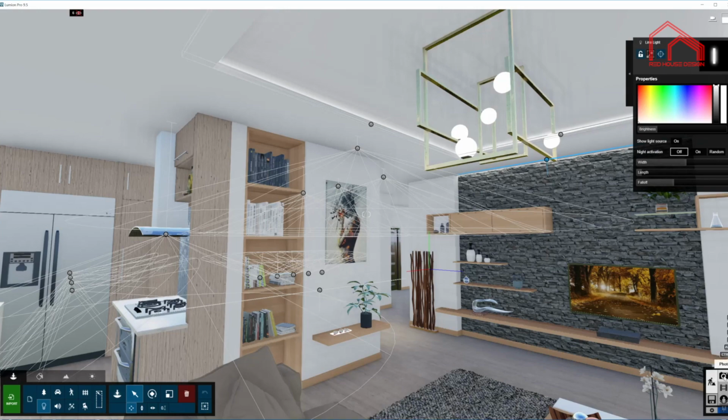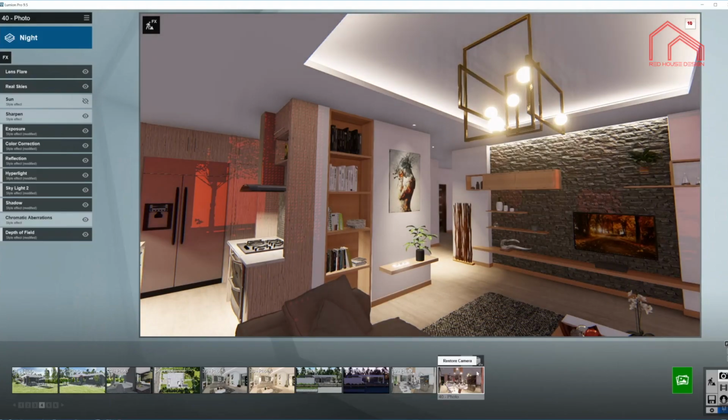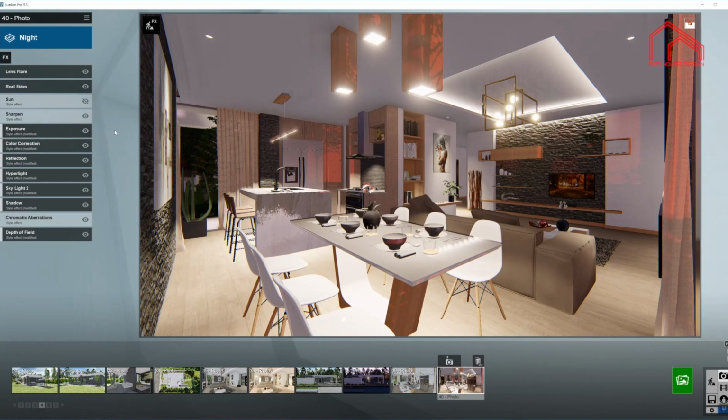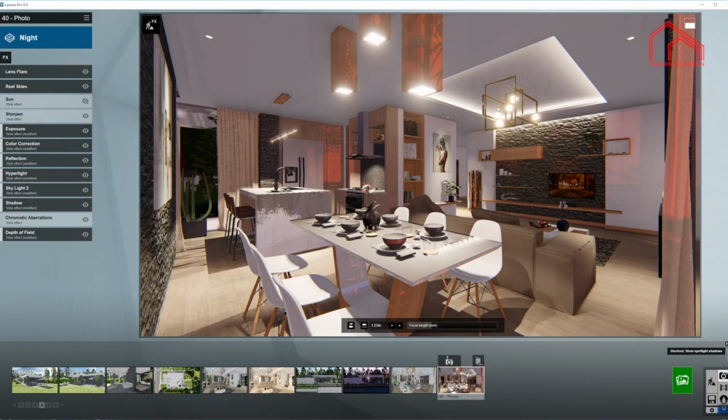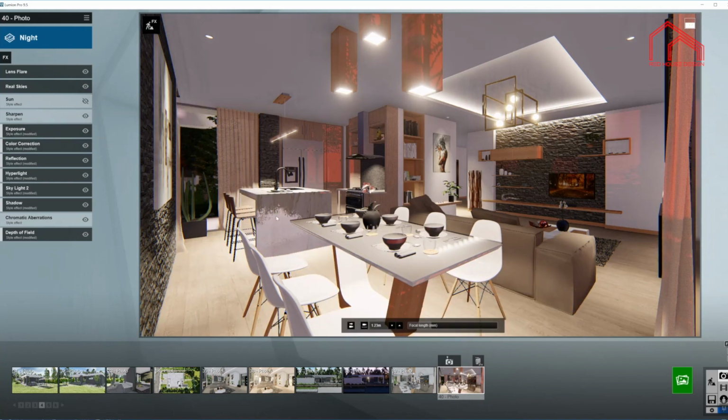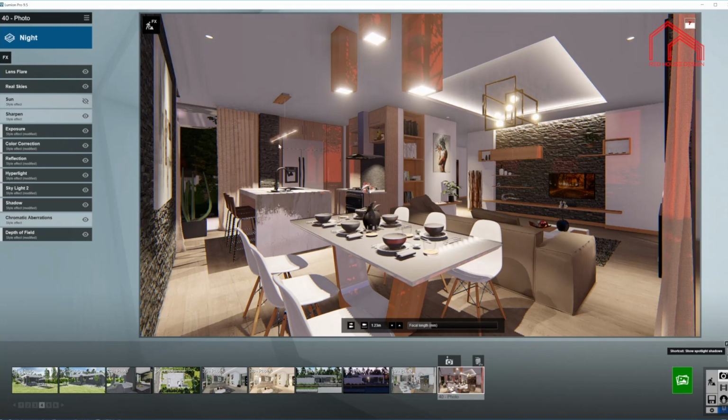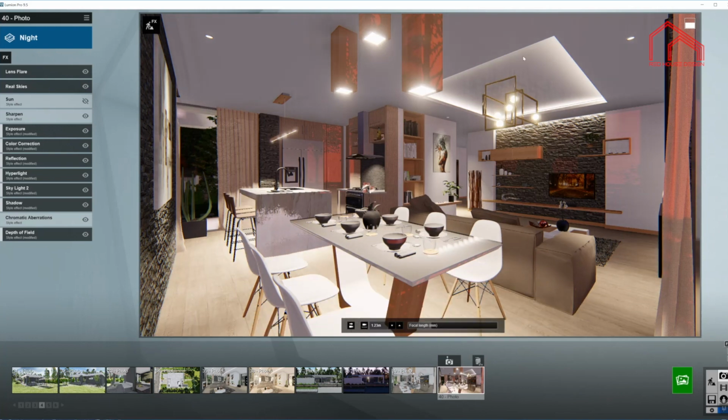So when we go to our scene preset in here and I press F8, you will not see any change in here. You see all these spotlights, they cast shadows. These line lights, they do not cast shadows, and also they would go through the material. So if we go on the other side of the wall, you could see a little light being penetrated through the material. So be very careful with those types of lights.